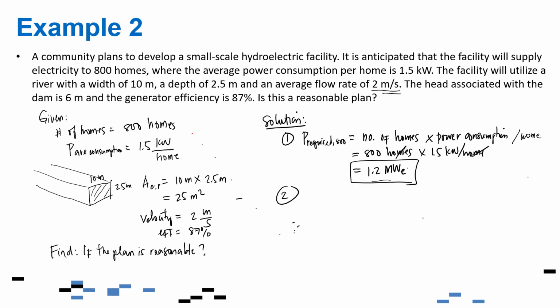So how do we do that? Of course, what is power? What is energy for that dam? Energy is basically the potential energy, which is mgh, and in terms of power, we can say E over T. So mgh over T is equal to m over T times gh. In this case, we are given the height. The gravitational acceleration is also known already, it's a constant. But we don't know exactly what the mass and the time are. So this is basically the mass flow rate.